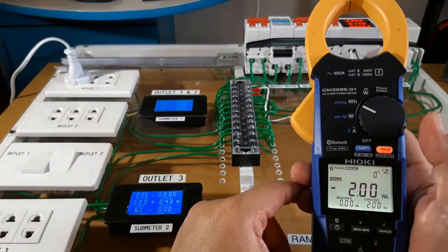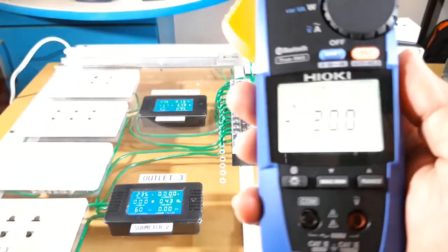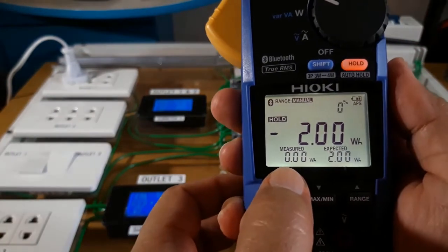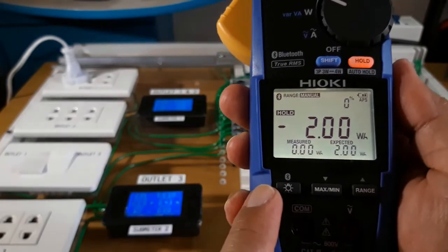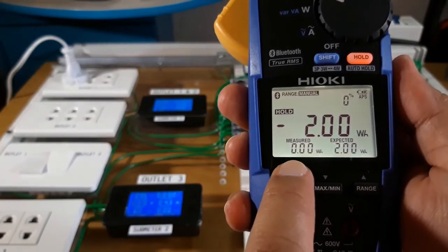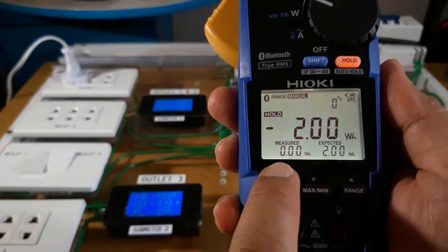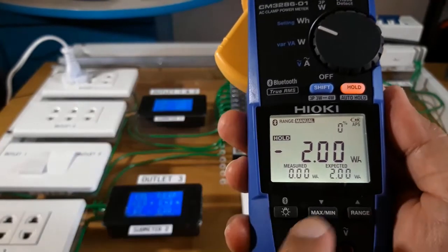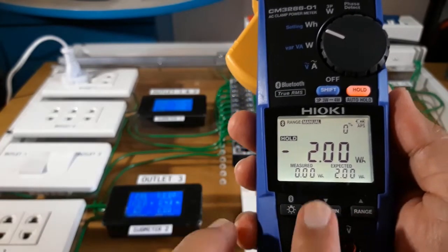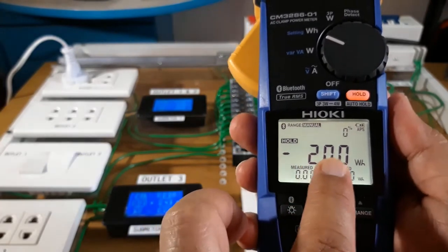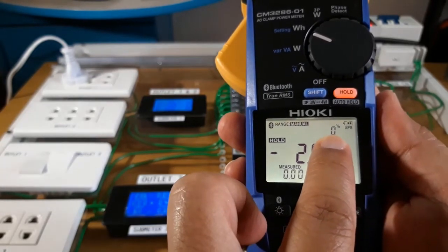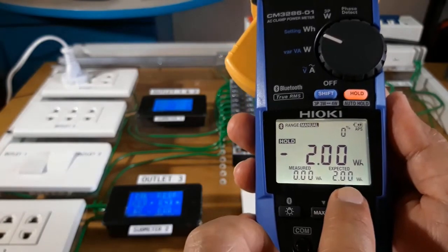and press the hold function again. On the screen now, we can see that the measured value here is 0 because we have not yet actually started using the instrument to measure the energy. But that's what the value here represents: the energy measured by this instrument. This is the expected energy within that pair of pulses, 2 watt-hour, and this value is the difference between the measured and the expected. And this upper value here, the percentage value, is the ratio between the measured and expected watt-hour.